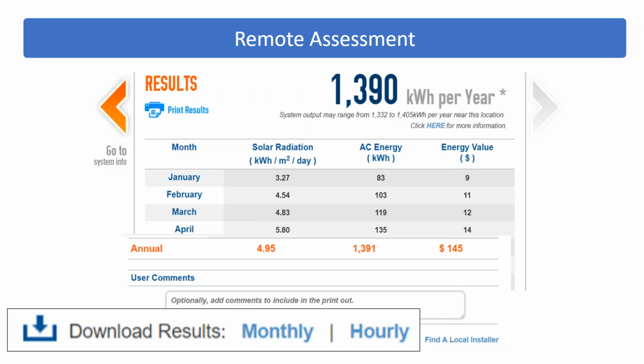So what we're going to do is we're going to get online and do a PVWatts example. When you get to the end screen of PVWatts, you will get a month-by-month printout of how much power the solar array will produce, as well as an annual total. The number one mistake you can make is to just end right there, because there's a whole other aspect of PVWatts.